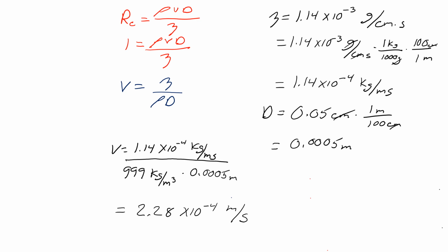So this is actually a pretty important step. Most of the time in groundwater systems, Darcy's law is valid. It's really unusual to find a situation where it's not, but you still need to check. Most of the time you don't have to worry about this, but you should just take a minute or two and do so.